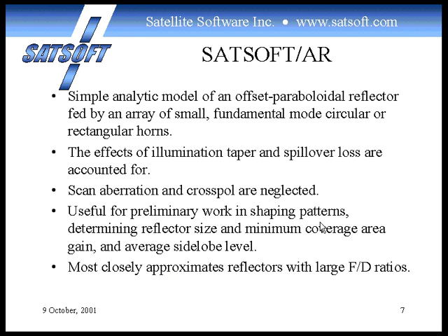SATSOFT AR is a simple analytic model of an offset paraboloid fed by an array of single or dual mode circular feed horns. Illumination taper and spillover loss are accounted for, but scan aberration and cross pole are not. It's a simple scalar model describing the amplitude of the pattern. The phase is set to 0. You cannot accurately determine the weights of a beamforming network using this model, but it is useful for preliminary work in shaping patterns, determining reflector size, minimum coverage area gain, and average side lobe level.